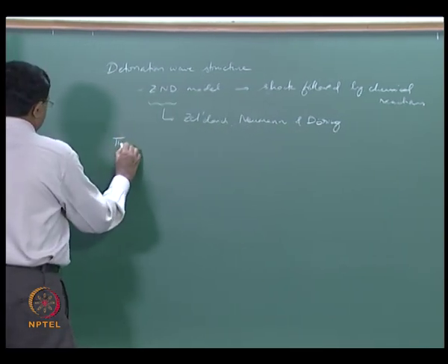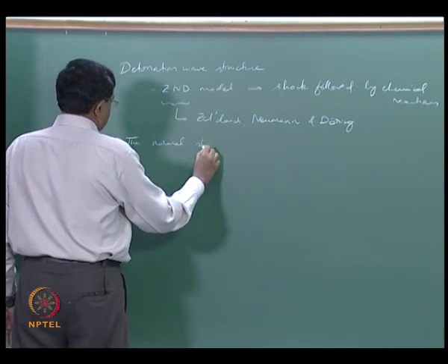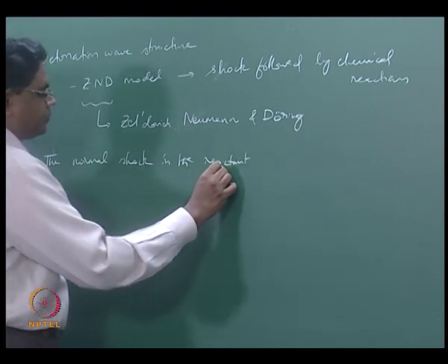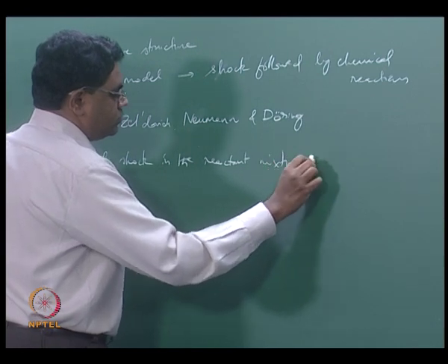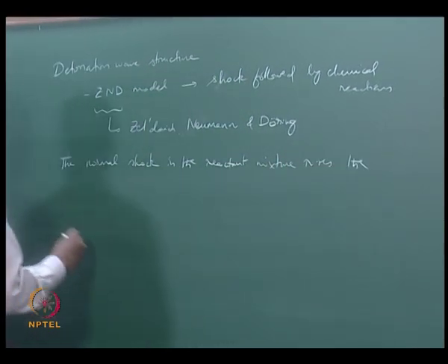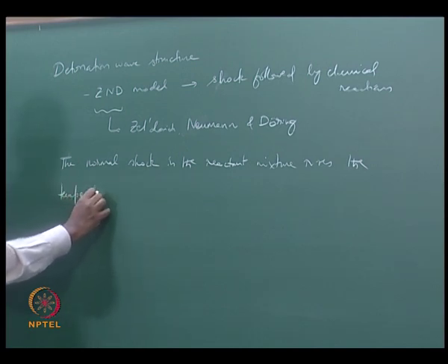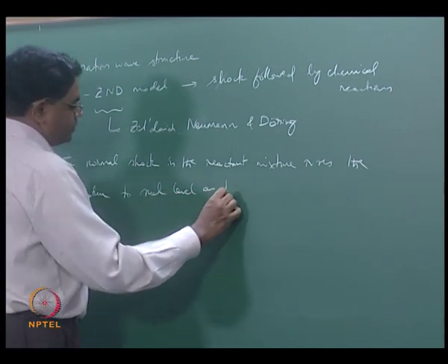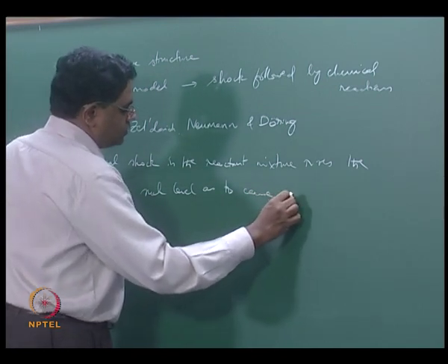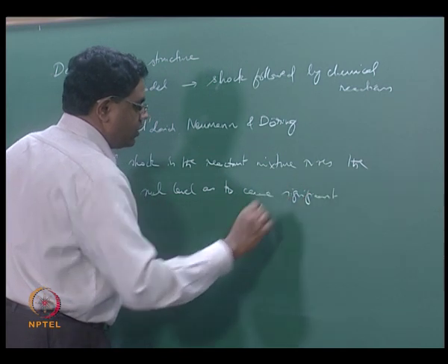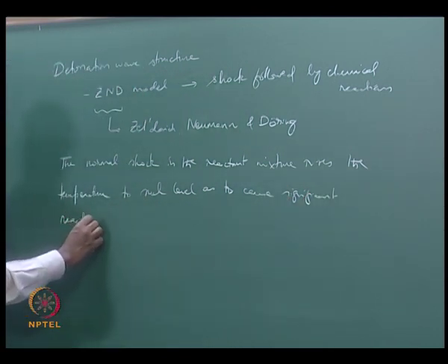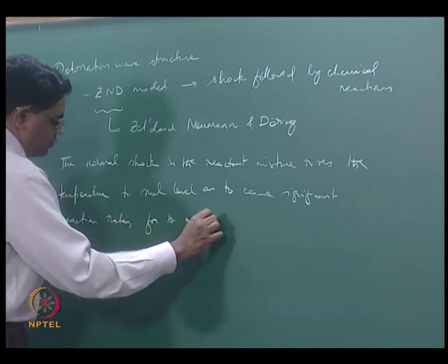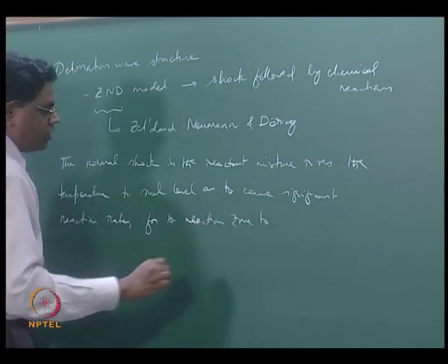So the normal shock in the reactant mixture raises the temperature to such a level as to cause significant reaction rates for the reaction zone to follow the shock.